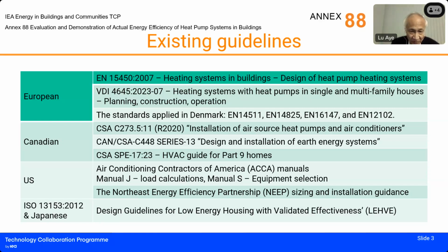You also need to make sure that the data available fits with the weather conditions that we will be running in. So there is a big issue here, with design methods relying on the data coming out of the manufacturer plus the testing method. Different countries have different testing methods and different standards, so we don't have a unified system of doing this. If you are a manufacturer of a heat pump and you export to other countries, you will see that difficulty. So this is an important aspect.